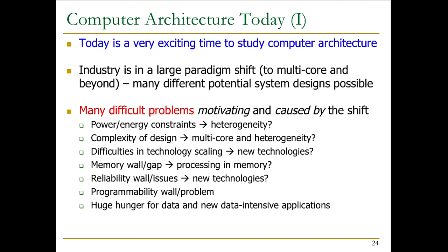Memory is a huge problem. That's why we're starting this advanced course with memory. And memory has always been a problem, but as we saw yesterday, moving data from memory into the processor chip consumes much, much more power, 3 orders of magnitude more power than doing a complicated double precision floating point addition, right? This means that maybe we need to rethink the system, and this is already happening in the field. Maybe we should do more processing close to the data, inside the memory, without moving the data. So we'll talk about that.